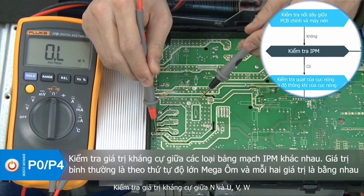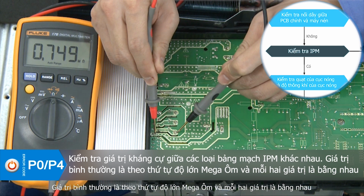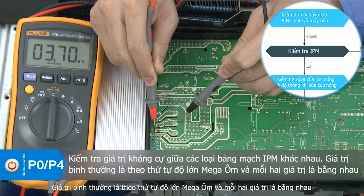Check the resistance between N and U, V, W. The normal value should be in the megohm order of magnitude, and each two values are equal.